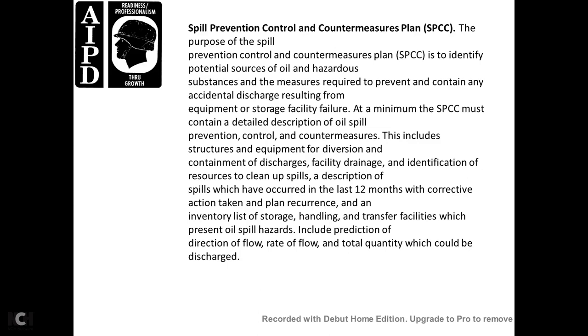All right, the spill prevention control countermeasure plan, SPCC. The purpose of the spill prevention control countermeasure plan is to identify the potential sources of oil and the measures required to prevent and contain accidental discharge resulting from equipment and vessels. The minimum requirement is that the plan must contain a detailed description of oil spill prevention control countermeasures.